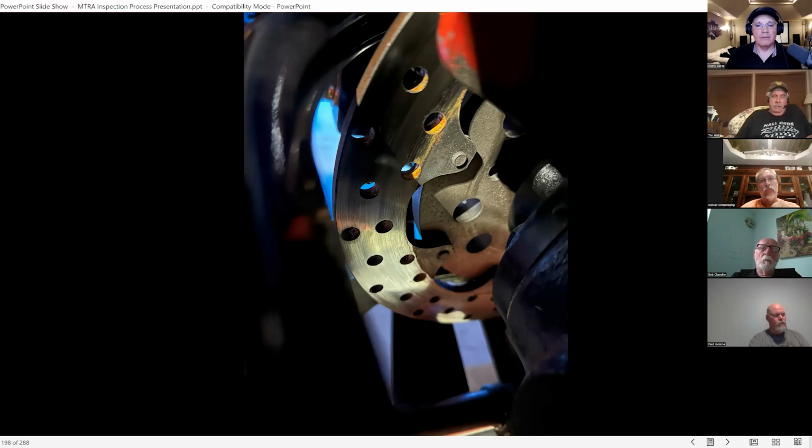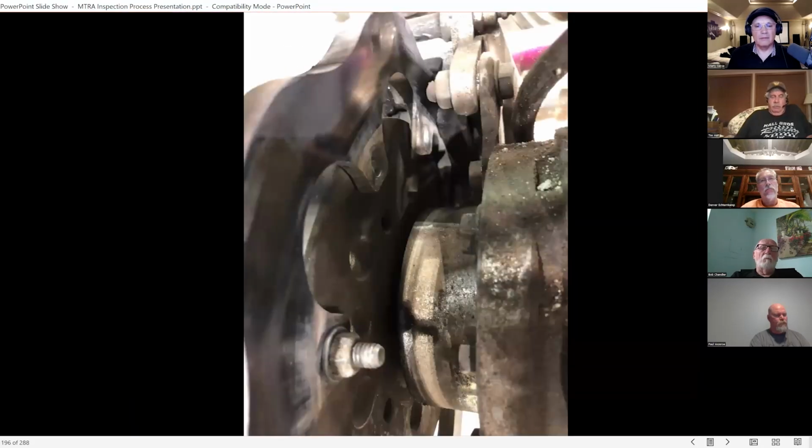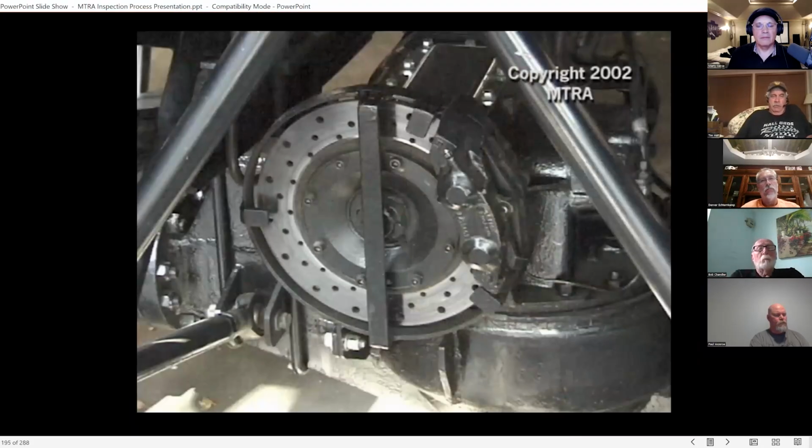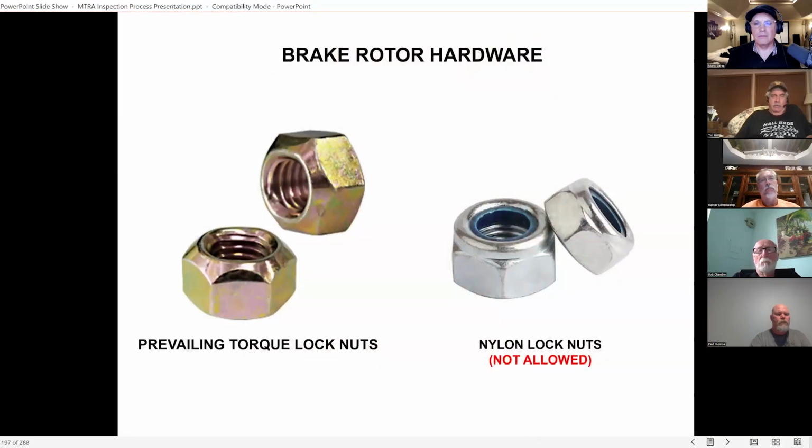Yeah, look at the pads. Make sure that they're not worn down too far, and that the pistons aren't sticking out of the caliper too far. Another thing we've noticed a lot is that the pads will wear, and up on the top, they don't ride down on the rotor perfectly. They stick up off the top a little bit, and they'll wear, and then they'll touch. And then the brake is essentially worthless because the pads will smash together, but they're not clamping down on the rotor enough. So be aware of that.